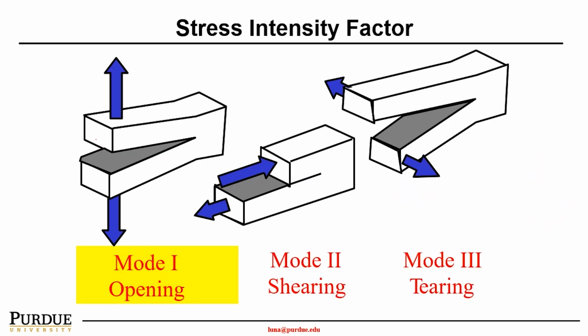So as discussed, we will look at Kc. Kc is a stress intensity factor. So C is the critical stress intensity factor. It means when that value reaches the critical point, when the crack becomes critical, or the length of the crack has grown substantially, it becomes critical. Specifically, we were looking at one type of stress intensity factor called K1C.